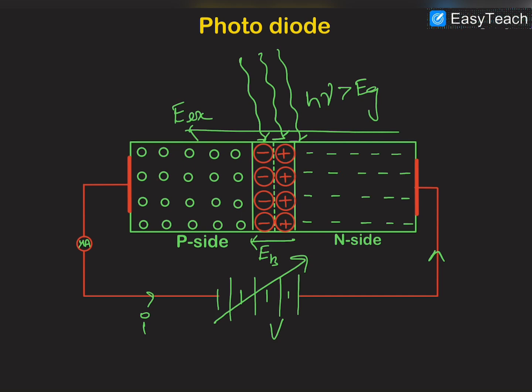We can also say that this complete diode is illuminated with eligible photons having energy greater than the forbidden energy gap, and all the electron hole pairs formed in this complete diode are minority charge carriers: electrons in the P side, and holes in the N side. Those electrons and holes flow according to the electric field, and a current is formed.